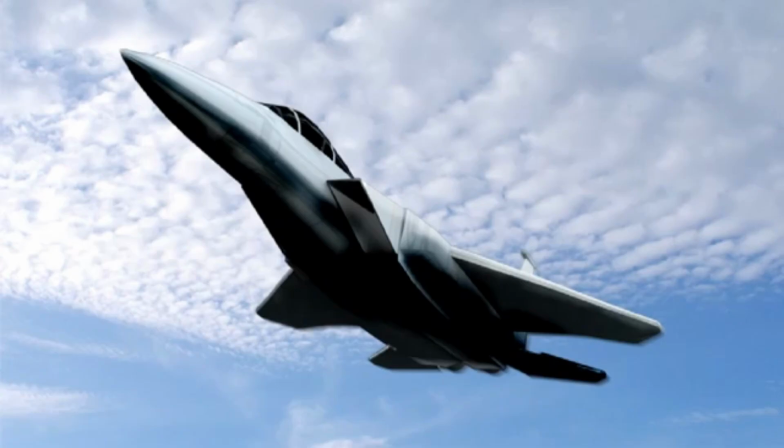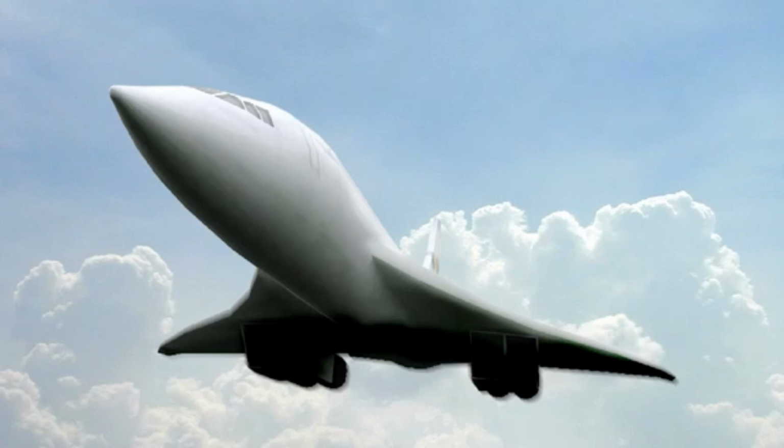Maximum climb thrust. This power setting is equivalent to max continuous thrust, and is selected to give the best angle of climb speeds. Maximum cruise thrust. This is a power setting below the value of maximum continuous thrust. Maximum cruise thrust can be used, for instance, if the aircraft has to climb more quickly than normal because of a terrain clearance requirement, or in order to respond to a request from ATC for a higher rate of climb.